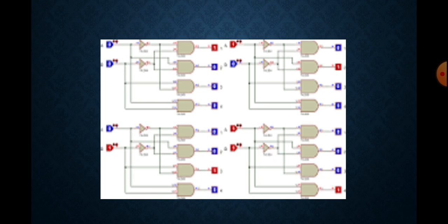Here we are using a 2 to 4 line decoder. An address decoder is a binary decoder that has two or more inputs for address bits and one or more outputs for device selection signals. When the address for a particular device appears on the address input, the decoder asserts the selection output for that device. A dedicated single output address decoder may be incorporated into each device on the address bus, or a single address decoder may serve multiple devices also.